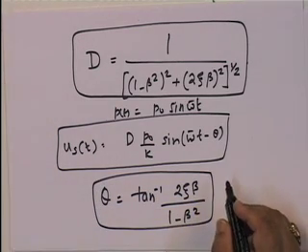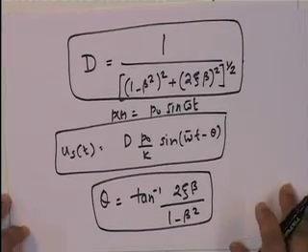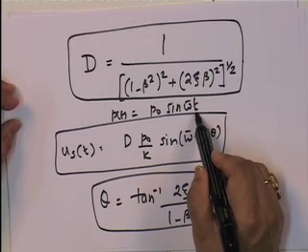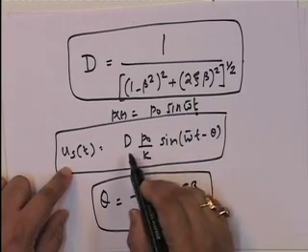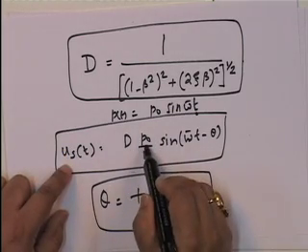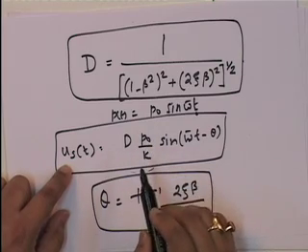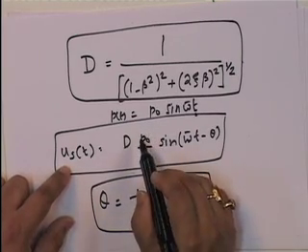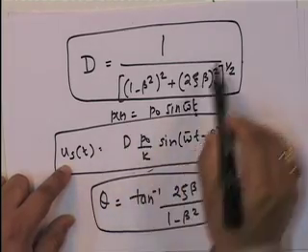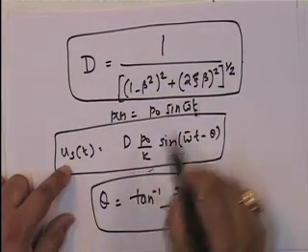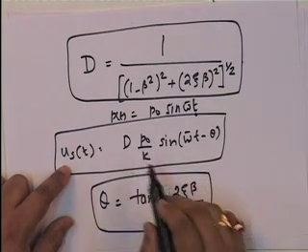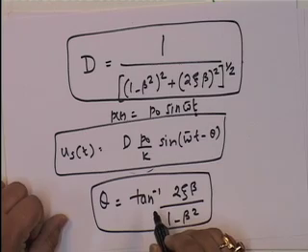So, in other words, if we go back, what are we saying? We are saying that, look at this, if you have a loading P naught sine omega bar t, then the steady state response is d P naught upon k. Note that the amplitude of this is d into P naught upon k. Did you see this very interesting part? What does the peak steady state response become? d into P naught upon k, where d is given by a particular parameter. So, note that if I substitute in this parameter and get d, and I do a static analysis with d, I can actually get the peak response.